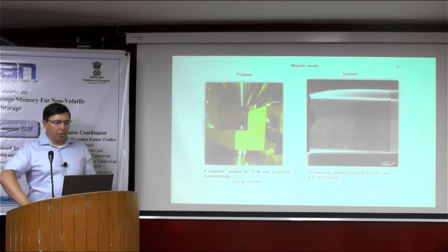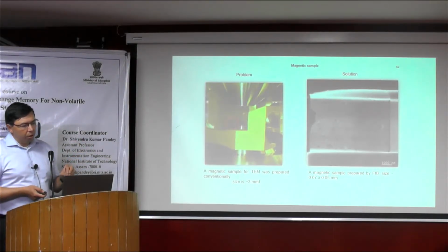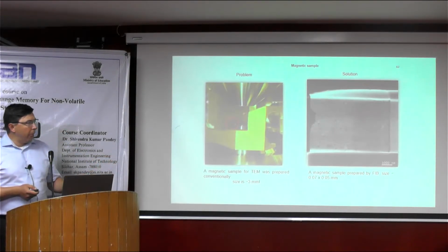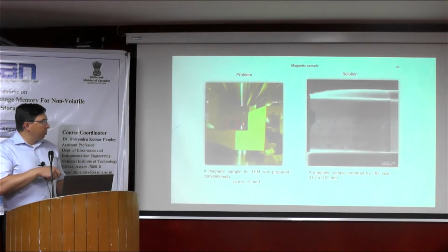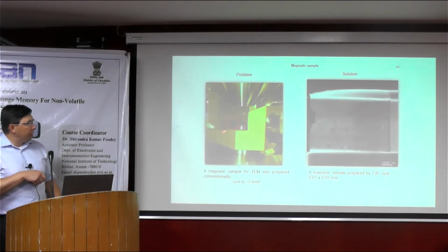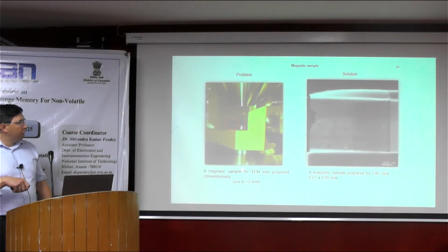Sometimes this is a very good method, because it's a local method. You prepare your sample from a small volume, and I showed you one trouble with TEM. If you have a large sample, like 3 by 3 millimeters, and if it's made of magnetic material, it was iron palladium, then if you do your work wrong, this material can touch the pole piece.